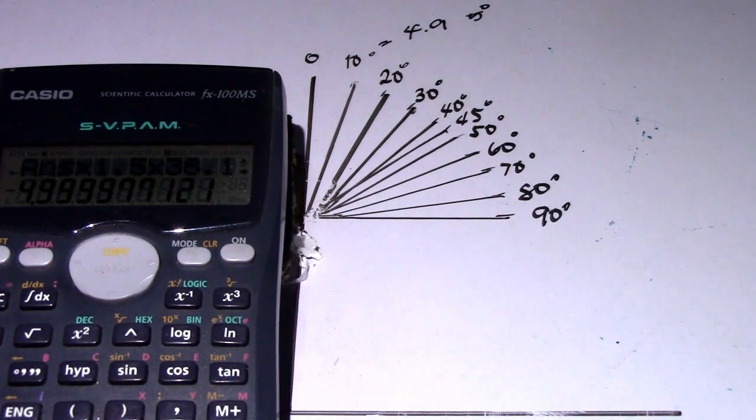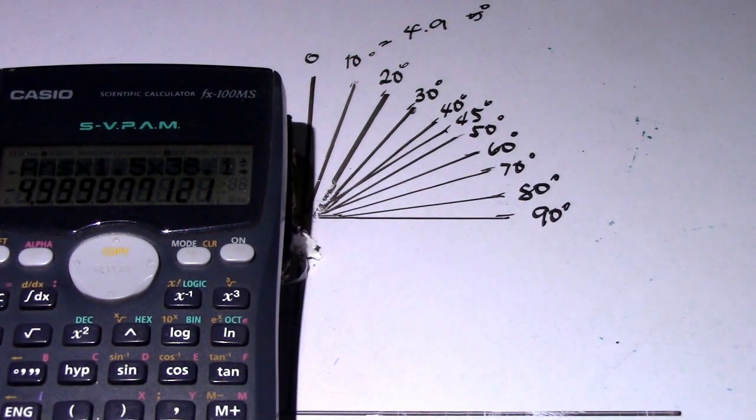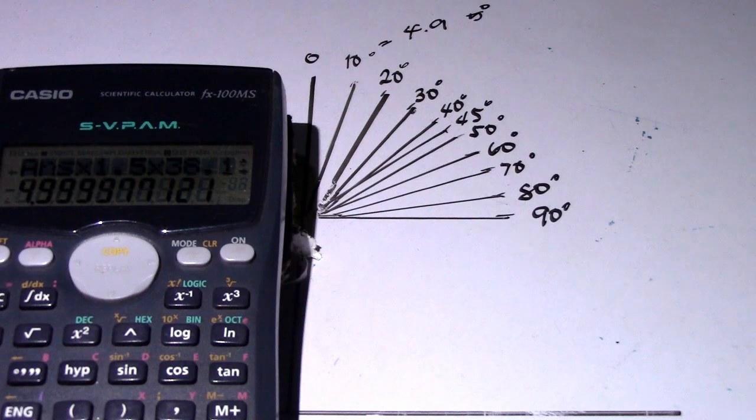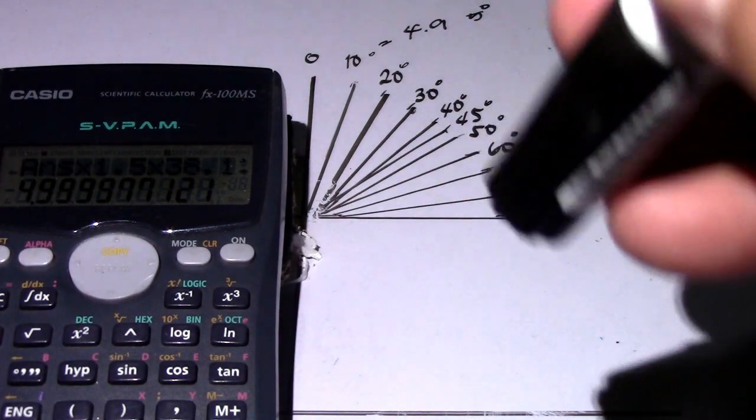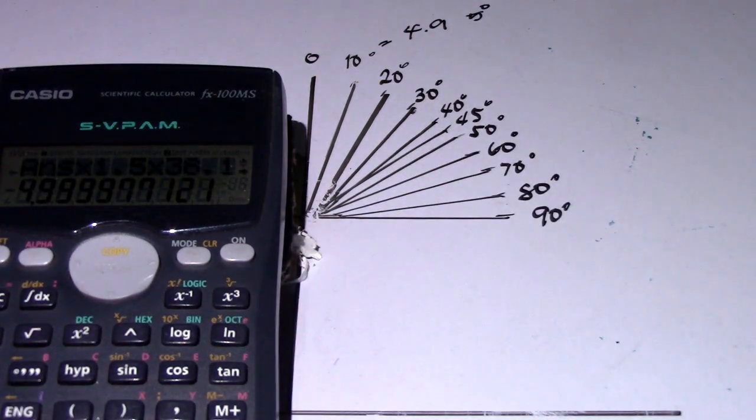So that one is how to compute any angle. You can use this formula if you have a 30 degrees elbow. You will find the takeoff for this 30-degree elbow using the same formula, and you can compute now what is the total spool you are using.